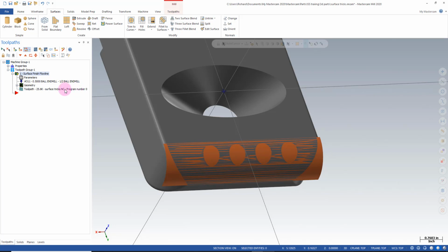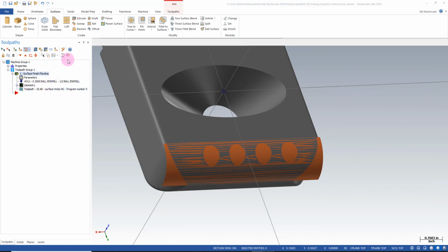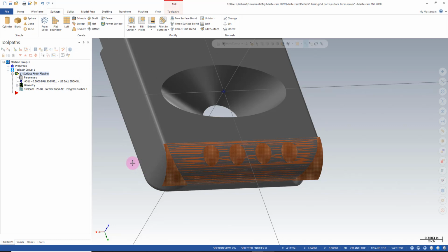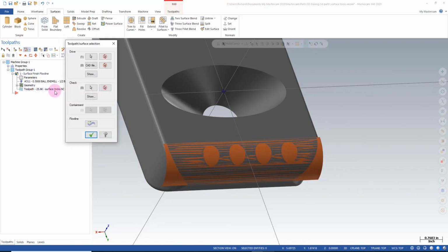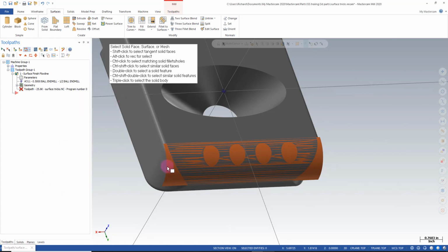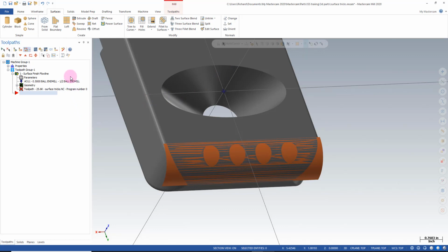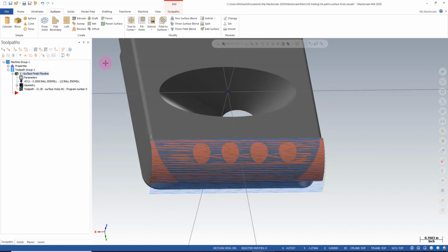If we go back and take a closer look at the toolpath now, you can see that I need to update it. So we're going to cancel out. And I'm just going to go quickly into geometry here and reselect the drive surface. And once I recalculate, we'll have an extended toolpath that will smoothly cut across the holes and extend past the length of the rough block potentially.